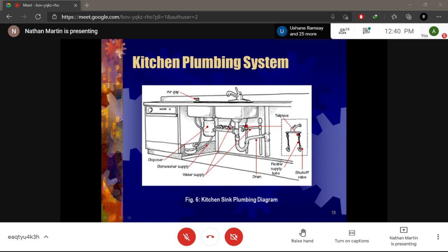And the thing you need to understand is that if this is not used in a long period of time, then you expect the water that settles here to evaporate after a period of time, right? So it's not foolproof from smell, but if it's in daily use or weekly use, then we don't have evaporation happening that fast to leave the trap empty.